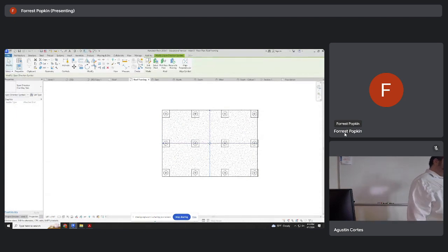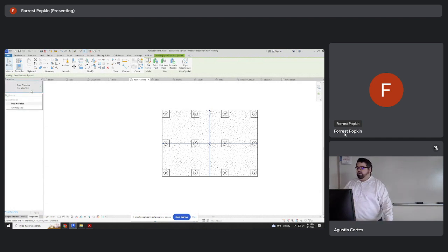So again, if you take materials, means, and methods, they talk about certain concrete structures being a one-way span or a two-way span. This has to do with how the rebar is configured. So in this particular instance, because our column spaces are pretty much uniform in both the X and Y, this would be what we call a two-way span concrete structure. We don't have to go into the nuances now, but just know that if it was more rectilinear in its spacing, that would be a one-way slab. This is a two-way slab.